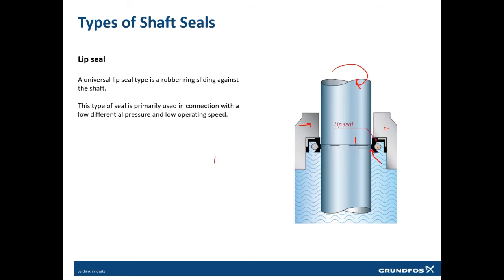But if you can see these marks here, these marks are because of the friction caused between two metals rubbing with each other. So this shaft is rubbing with this seal. This is called a lip seal. It is ideal in two situations. The first situation is low speed pumps and oil related pumps. Usually the oil related pumps use this lip seal arrangement.